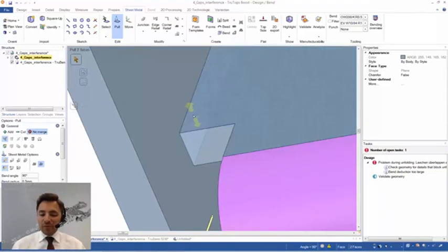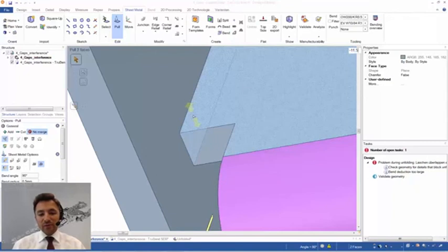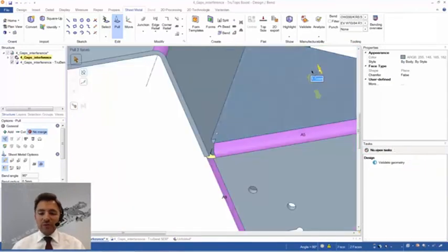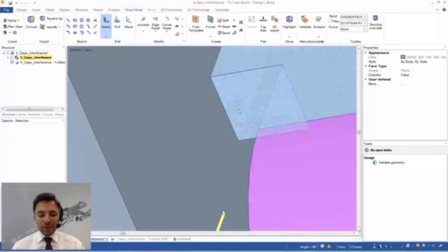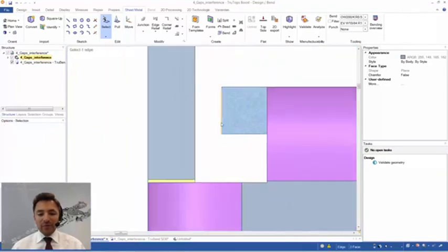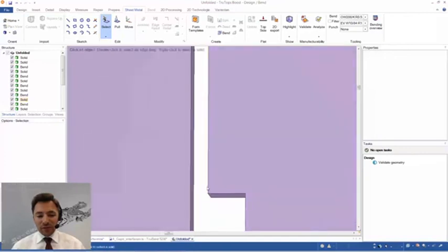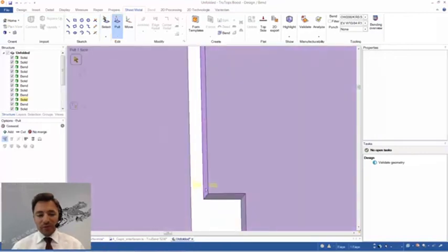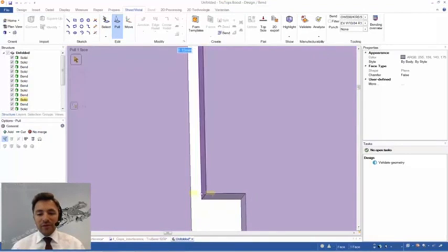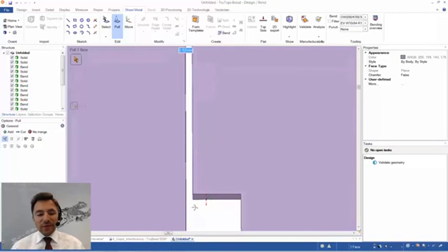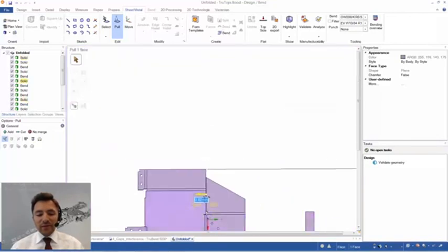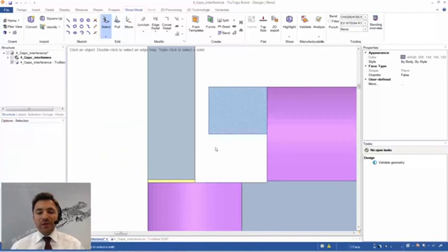So I pull that one by, let's say, minus 1.5 mm, and we should see a gap here. If I activate the front view, I see it has been moved, and of course I can still drag and drop it or drag it back by just pulling the face. And yeah, set another distance as I wish. So we have solved it.